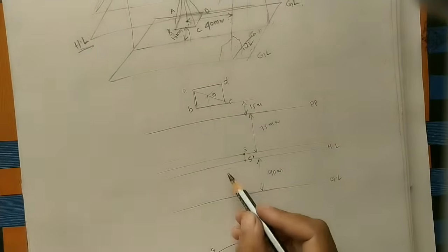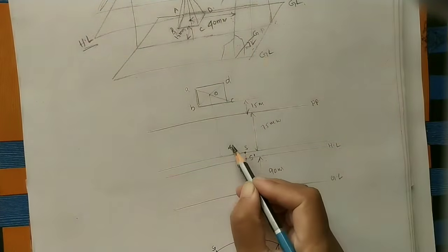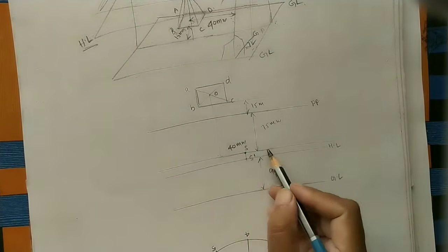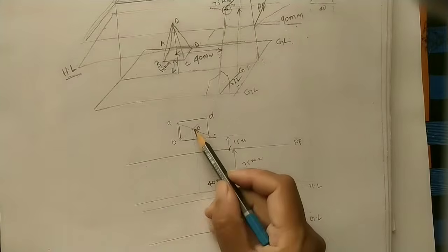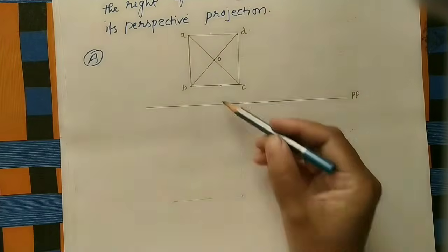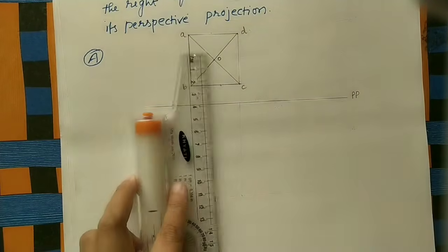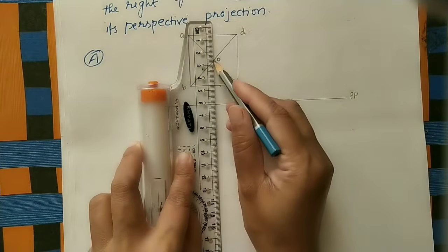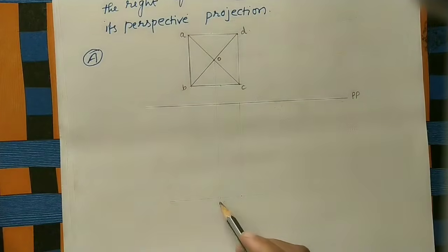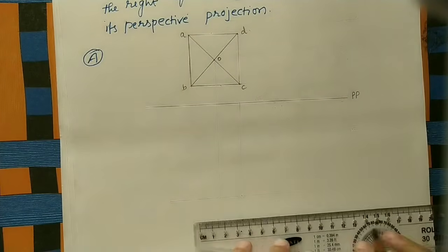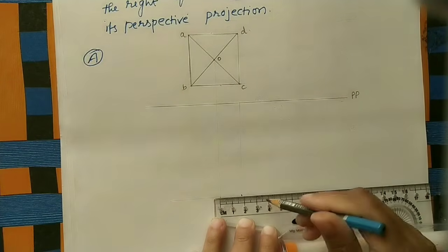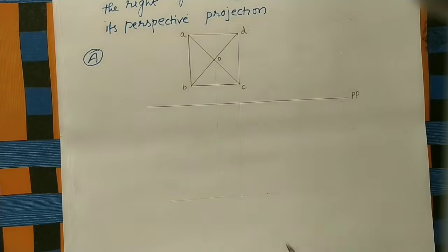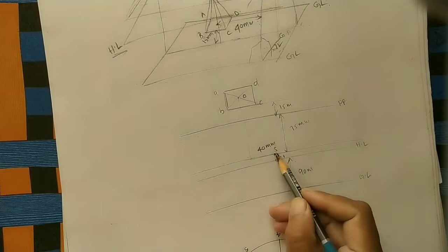Okay. So here from it take 40 mm distance from center of this to this station point. From this center it is 40 mm. So just do center line. Take this as the reference. Move up to the center. Just do one line. From center take 40 mm distance. Okay, this point is the station point. After 40 we have marked it.